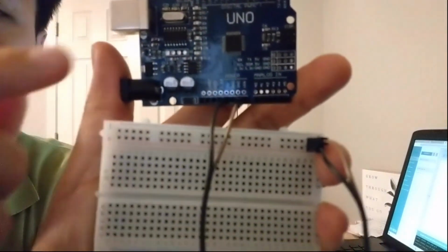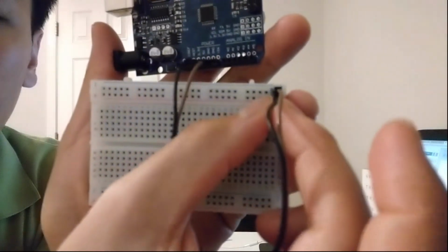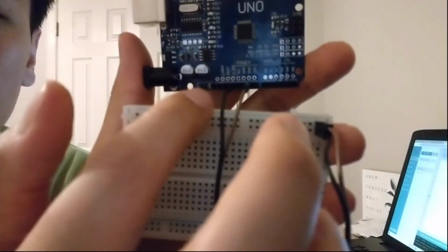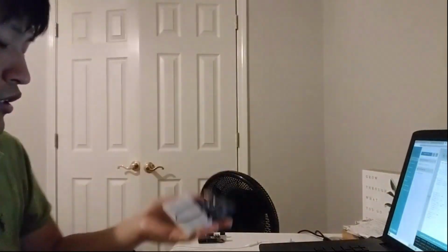It doesn't matter which one, you just put one there, okay? If you cannot see it well here, go back to the app because it shows you where it is. Just to repeat, the black one is in the positive and connected to 5 volt, and the brown one is in the negative, the top row, and connected to the ground, GND. Okay, next.